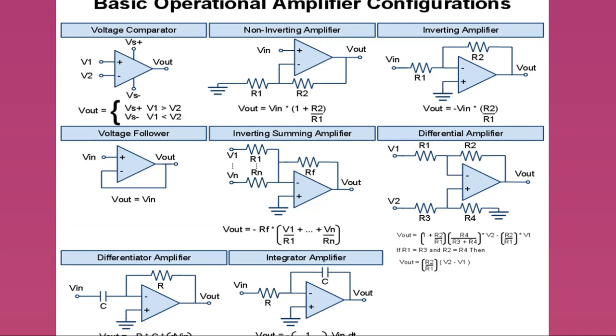You can use it as a voltage follower, kind of like a buffer. It'll still have a very high input impedance, a very low output impedance, but has a gain of 1. So that would mean it would operate all the way up to the maximum frequency of the gain bandwidth product. Use it as a summing amplifier, where you've got a bunch of analog signals, audio signals perhaps. It's what you see in an audio mixer, with all the slide controls. Those would all be these input resistors all summed together.